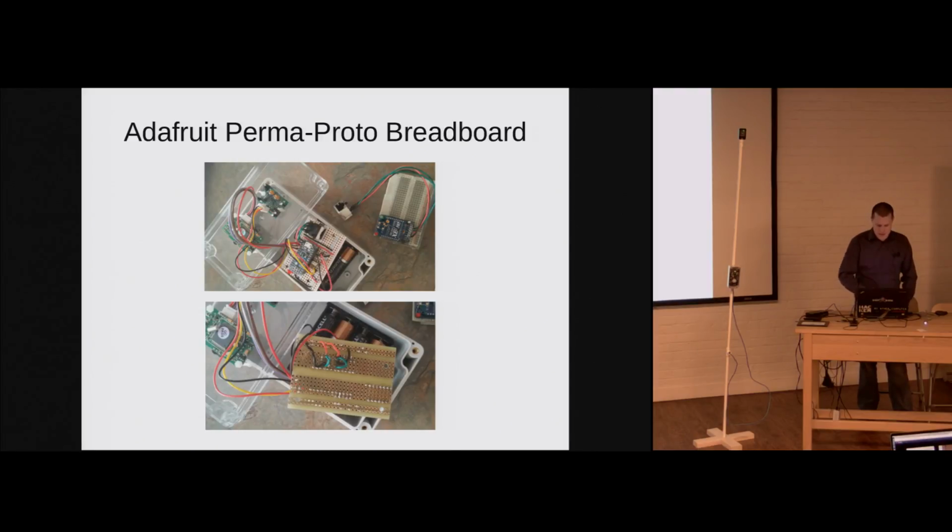And then it's kind of hard to see from the picture, but there's 2 little white jumpers to the right on the bottom of the microcontroller on the board. And those act as hardware feature toggles. What I wanted to do is have these test programs on the board. The main program on the board is responsible for detecting motion, taking the picture, sending it. I also wanted to have other programs that I could run while I was setting this thing up, so I could calibrate the motion detector and so I could make sure that I had visibility to the coordinator chip.